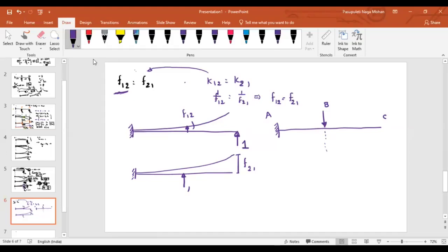I'm not talking about any bending diagram. I'm talking about the deflected shape. Triangle, sir. Let's say this is the point B. Is there any load acting in the portion BC? No, sir. If there is no load acting, then this portion will not bend. What will happen? This deflected portion will be linear.